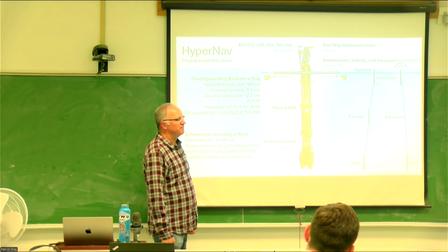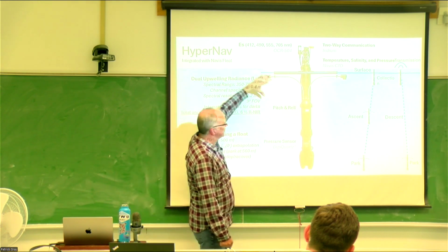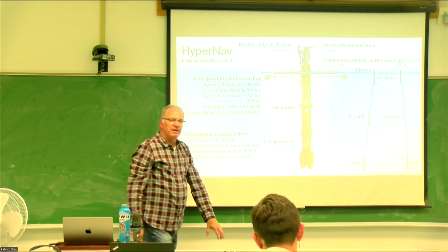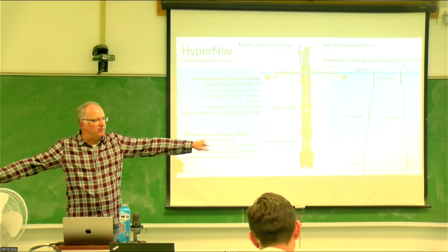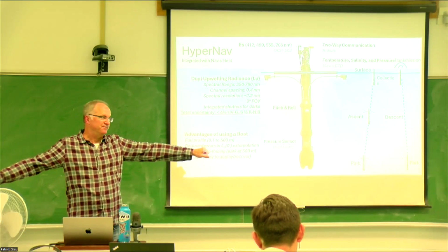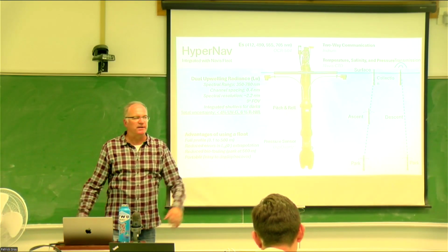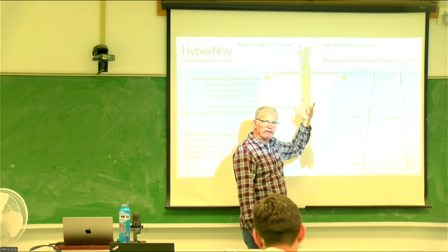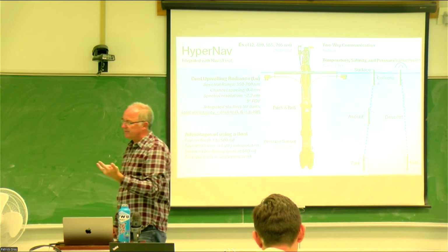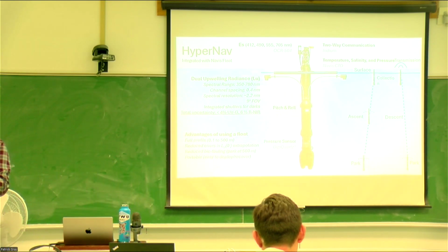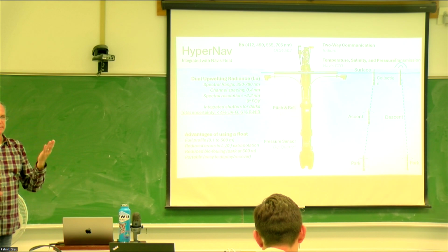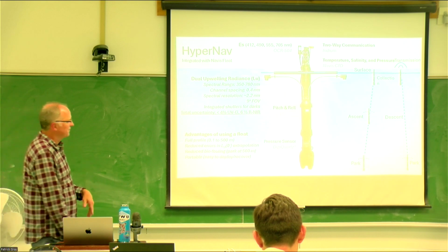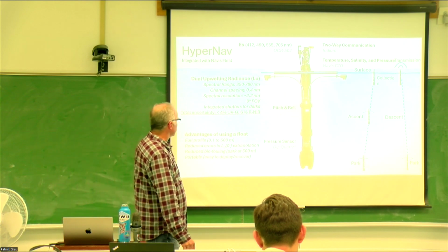Shadow gauge measurements. Correct. If the sun's here, it's casting a shadow, and now a portion of my light is in the shadow. That's why we have two, because we're always guaranteed one of them is not going to be in shadow. The other purpose is redundancy. What happens if one of these really gets banged, goes out of cal? Now I've got two redundant sensors, which is also a nice thing because it gives me a way to do a relative measurement of uncertainty. How far off are both heads? At least in the measuring.